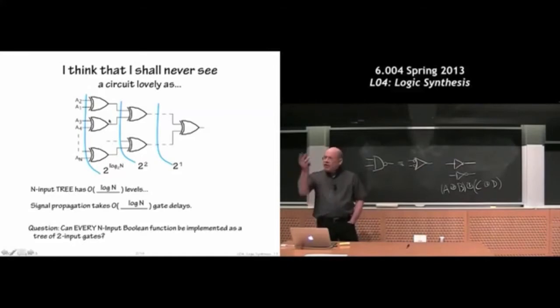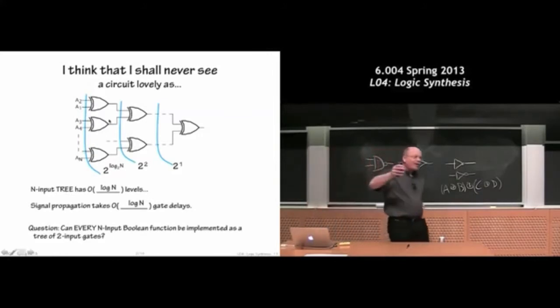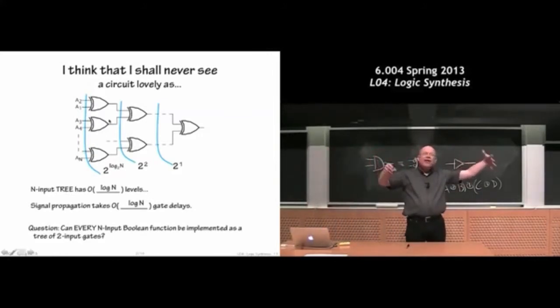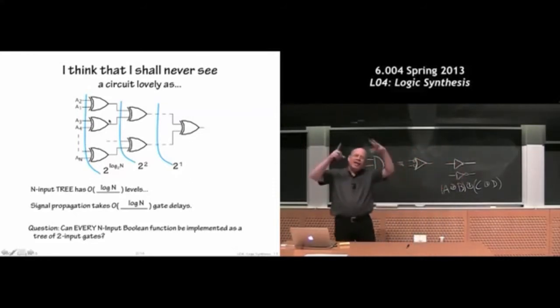The pesky thing, you're zooming around what I think of as the right thing. It's the inversion that's getting in the way, right? I can build a tree of AND gates and a tree of OR gates. Positive logic trees up very nicely. This inverting logic, because each gate inverts, now I'm stuck on the next layer dealing with inversions. And so the trees get a little bit more complicated to build. If I wanted to build a 57 input NAND gate, maybe what I would do is build a tree of ANDs and then just put the inversion at the end, and I can build the tree.